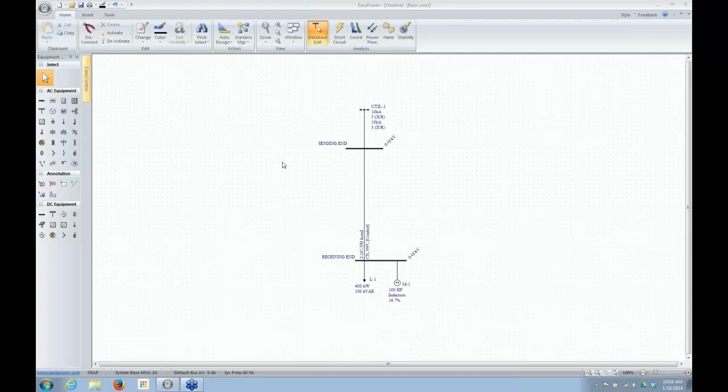In a typical industrial system, if you just take all the load as connected load and run a power flow at 100% connected load, you're going to get a very unrealistically high value of load, because not all the equipment is going to be on at the same time, and virtually none of the equipment that's running will be running at 100% of its rated amps, full load. So part of the problem in doing power flow is coming up with a realistic model for what your actual loads are going to be, and we'll talk about that in a little bit.